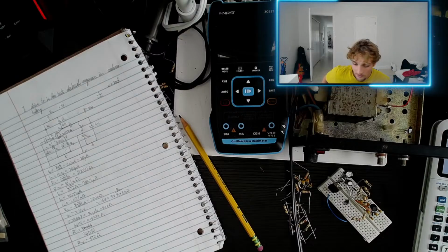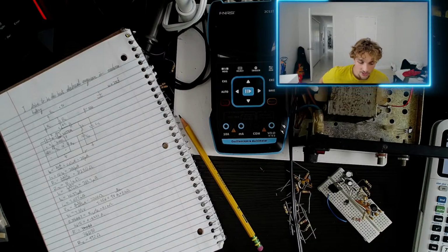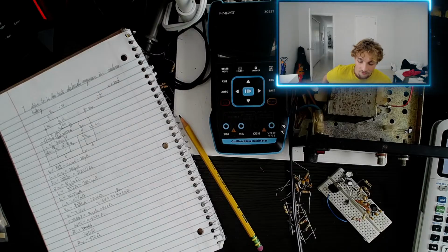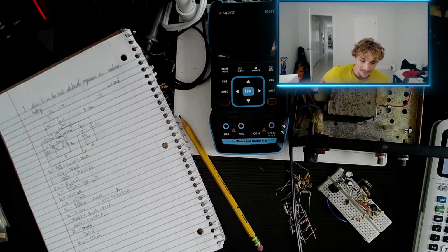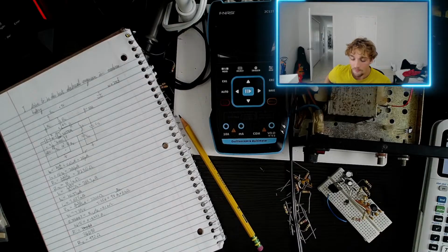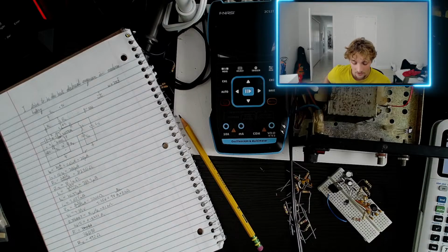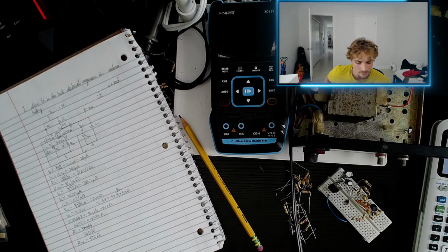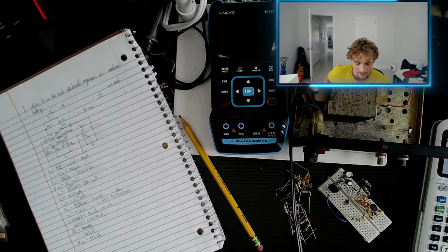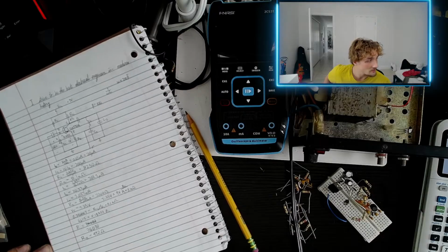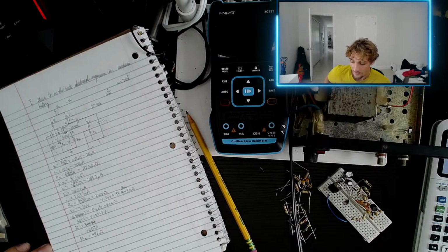We can compare the output voltage to the input voltage and measure our gain. I have an auxiliary cable here with an aux port that I can plug into my phone. My phone has a signal generator on it, and we can have 2 channels recording on the oscilloscope. One channel records the in, which gives me my voltage value, and the out would give me my other voltage value, right? Then we can compare the 2 values to calculate our voltage gain. That's probably going to be much easier than theoretically calculating voltage gain, because that's quite a lengthy process. That's actually the first time I've had that idea, and I think that's the best idea.